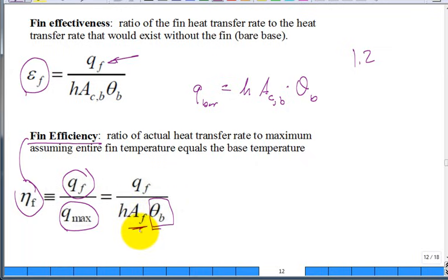And this area is not the cross-sectional area, but it's the area of the fin. If it's a round one, it'd be perimeter, well, even square, perimeter times L, wouldn't it? Neglecting what's on the tip. Just that's the convective off the side. That'd be the area of the fin. So what about this fin efficiency? Well, you'd like it to be high, but, well, it's another metric. Okay.